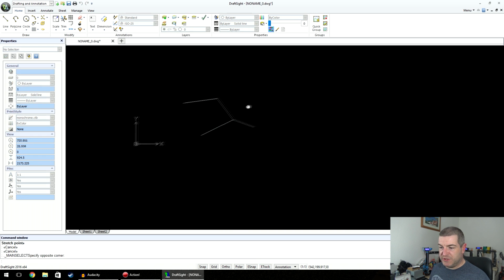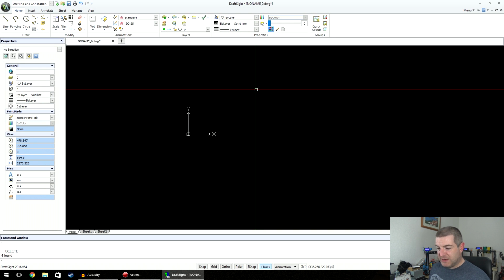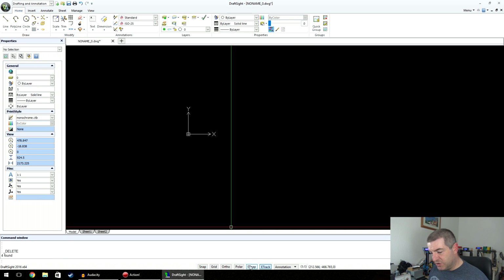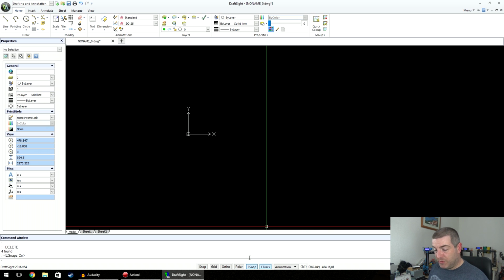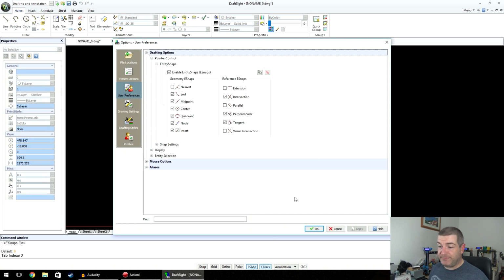So what we need to do is we need to start snapping. Now, down here, there's something called eSnap. I'm not talking about snap and grid. Don't use them. I'm talking about eSnap. So we turn eSnap on and nothing happens. Okay? So what we're going to do is we're going to right click eSnap, and we're going to say settings. And now we get this cool box with a lot of tick boxes in it. And it says enable entity snap. Yeah, that's what we want.